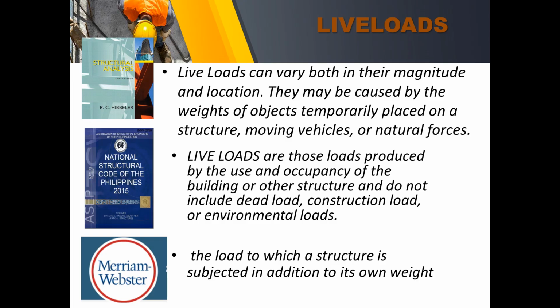Next, we have the live loads. Live loads can vary both in their magnitude and location. They may be caused by the weights of objects temporarily placed on a structure, moving vehicles, or natural forces. Actually, live loads are transient in nature. Of course, they come and go. It's not permanent on the building system.